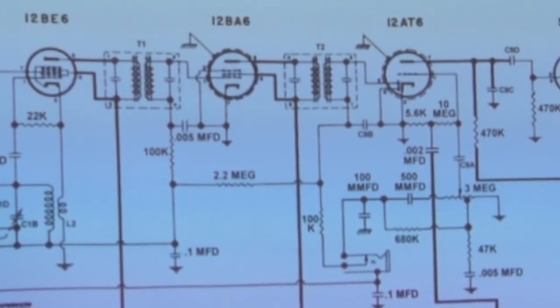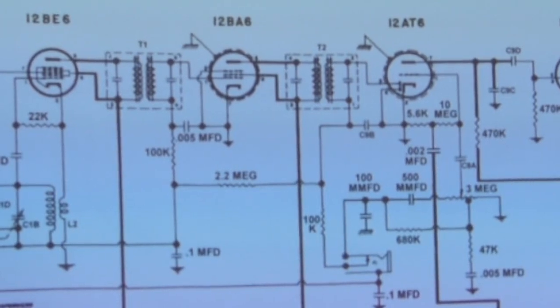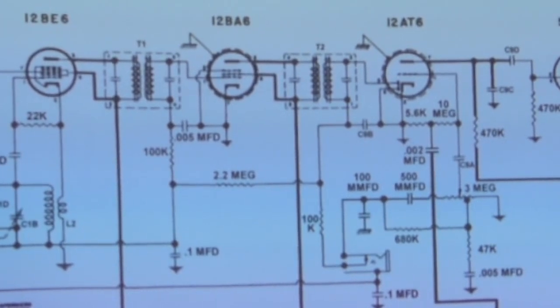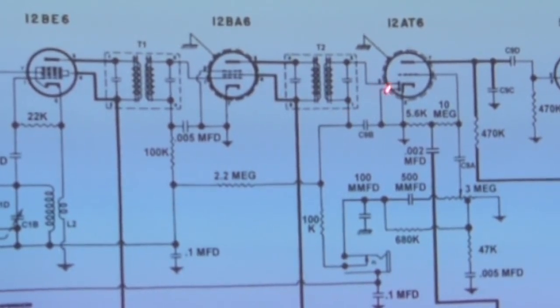I think also in Rick's presentation he showed the effect of that. You know, you could kill your output signal on the back. Even if you have a shorted turn, it doesn't have to have a whole number of turns. Even a single turn will do it. It will collapse the inductive field and you'll fail to get a signal.